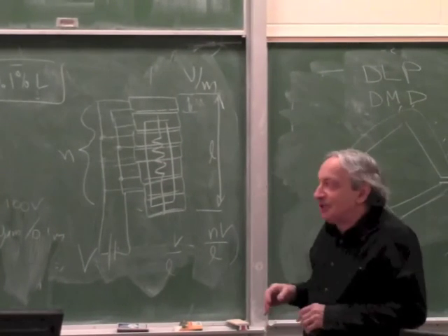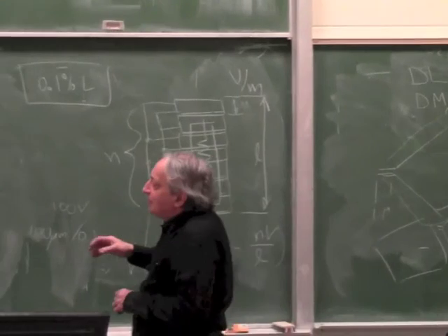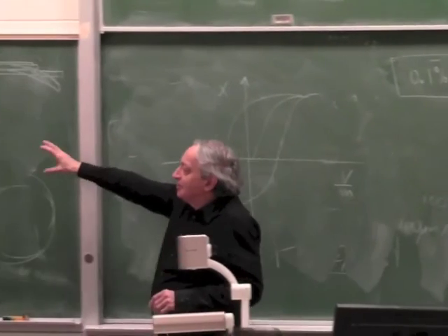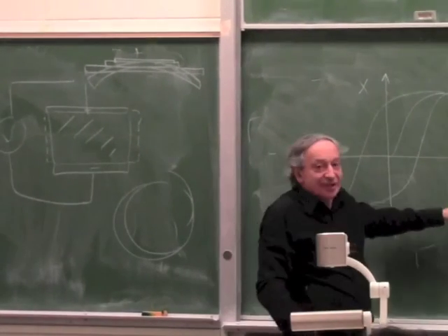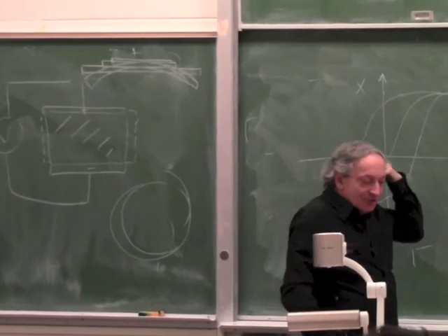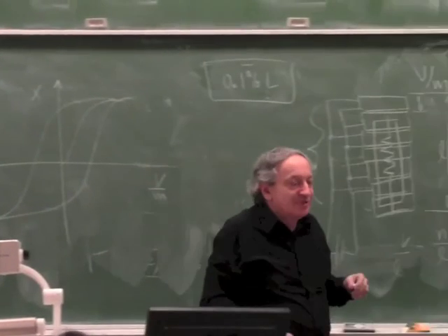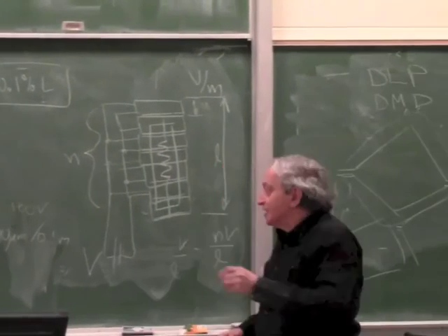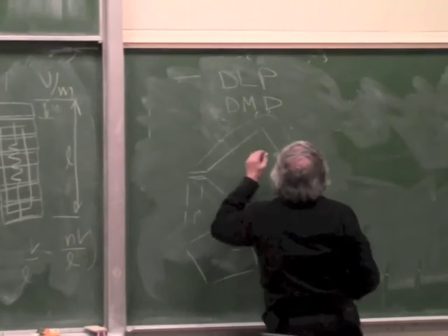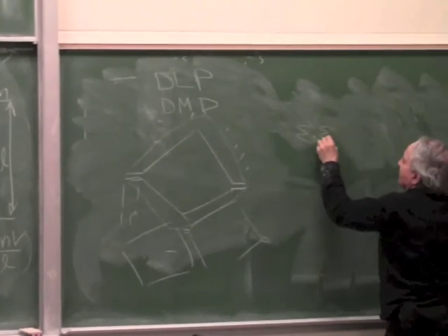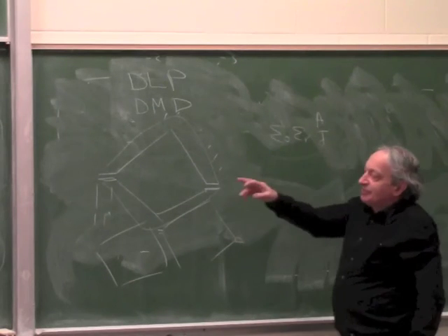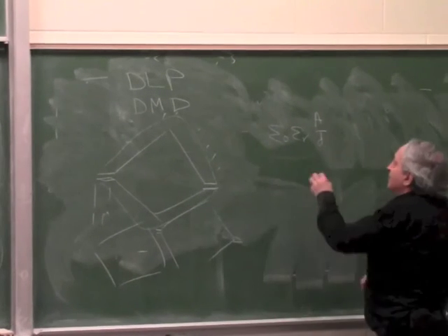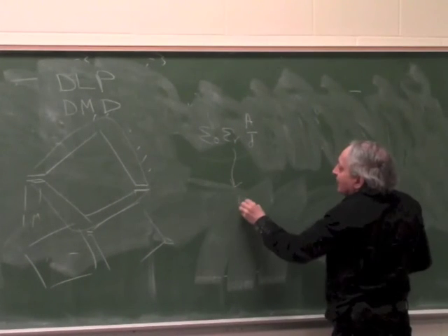It turns out the materials which have a high piezo coefficient, which is how much it moves per volt per meter, also have an enormously high epsilon r. Like we said, capacitance is epsilon 0, epsilon r, A over D. Now the materials which have the best piezo property have an epsilon r on the order of 100,000.